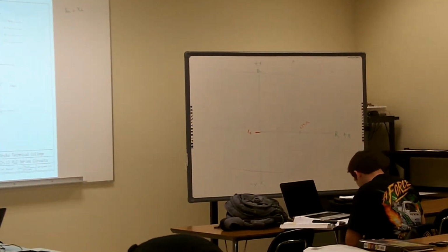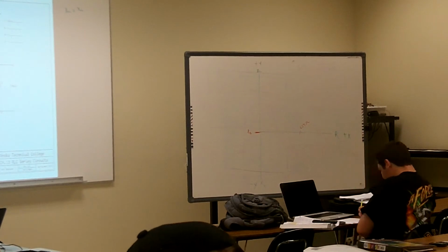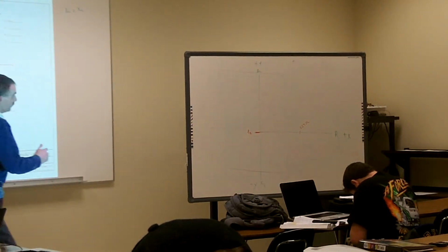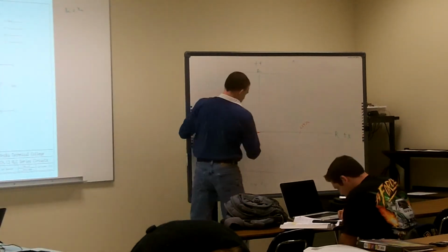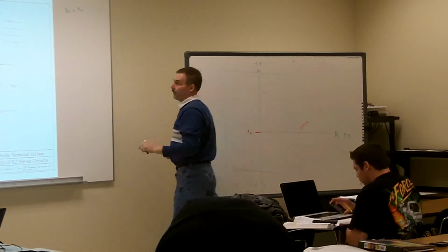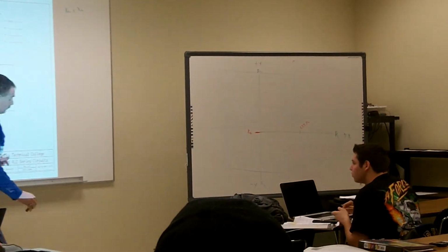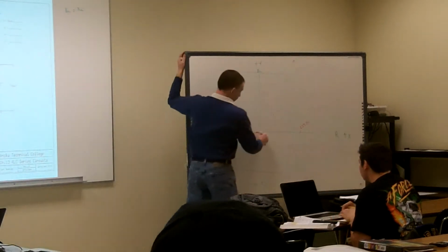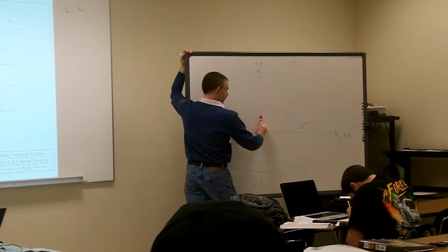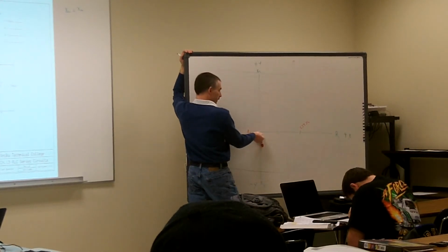So now once I have my X and I have my Y, I can go ahead and do all my other calculations. Since I know that my X of T is at 0, and if I want to find the total impedance of my circuit here, my ZT, here's my ZT, it's a vector. It's going to be somewhere between X of L and X of C. So where is it in this particular case?